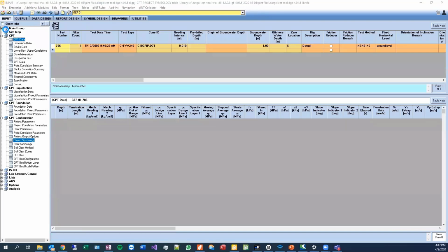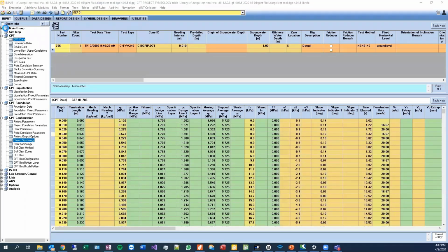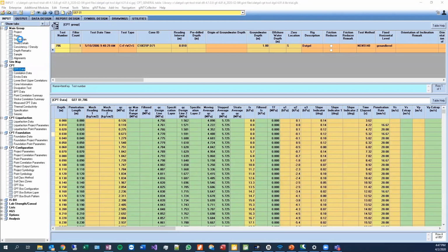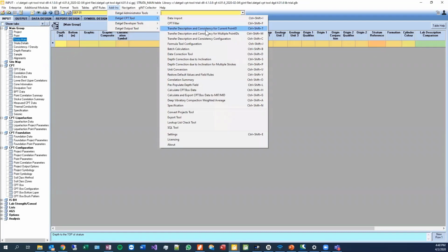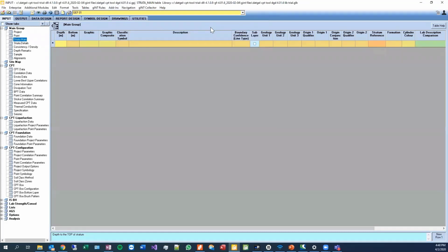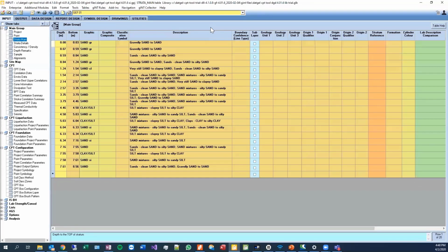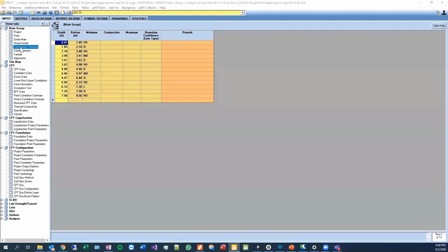All right, so next I'm going to summarize the soil behavior type data into the strata main table as an initial summary of information. I don't expect people to always use this as what you report to your customer. There are ways to make this less layered. There are some settings. It also calculated this consistency, density, or soil strength data. All right, now let's go to output.